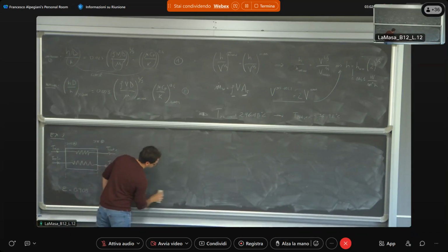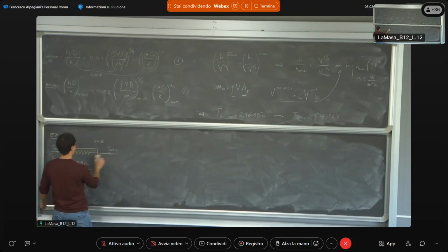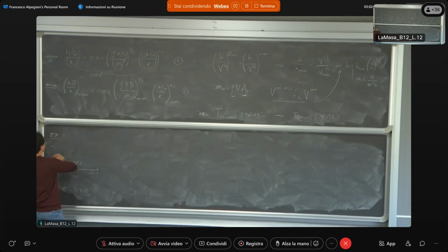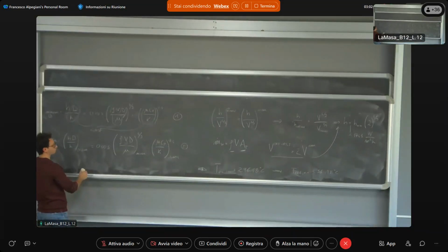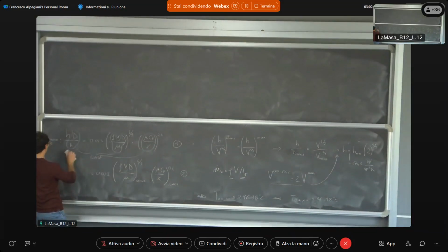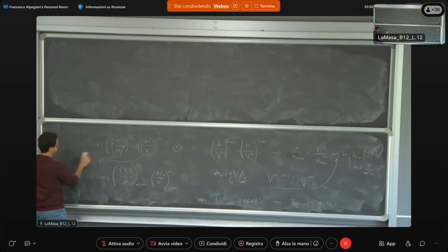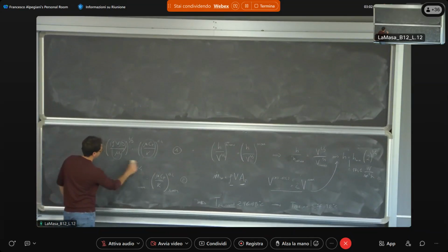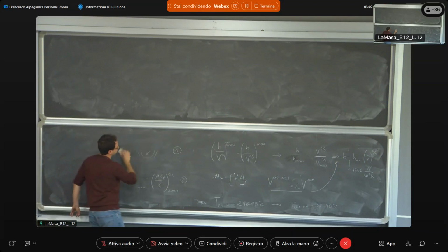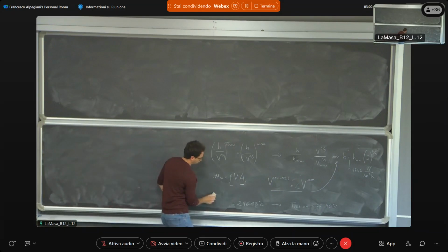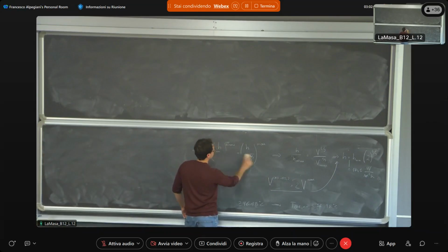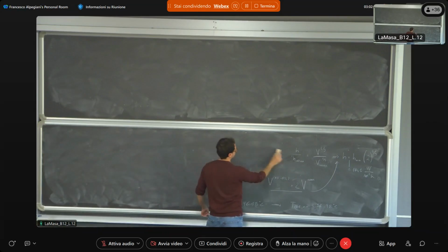Then we have this reactor which has a catalyst inside, which favors essentially the reaction to form as products CO2 and hydrogen. Okay, the water gas shift reactor is used to increase the hydrogen content on molar basis in the exiting stream from the reactor.